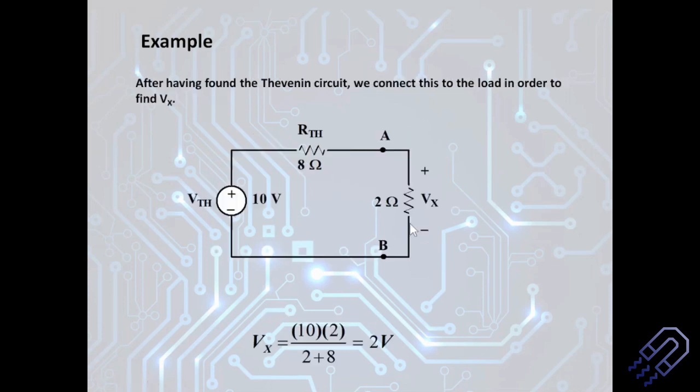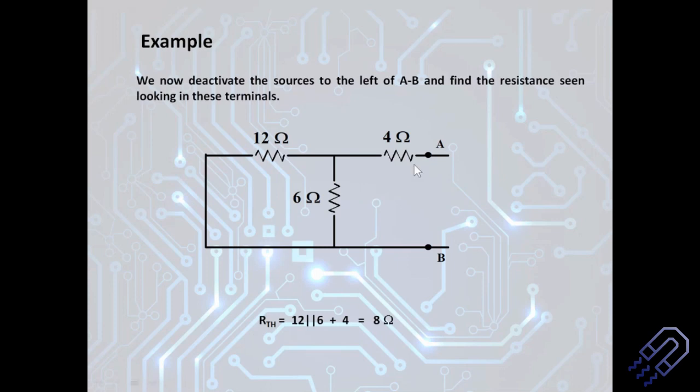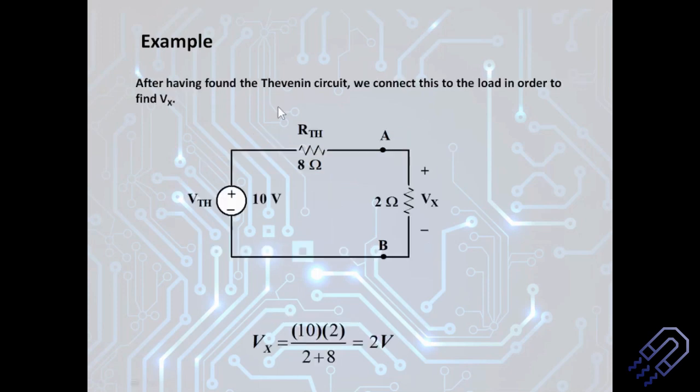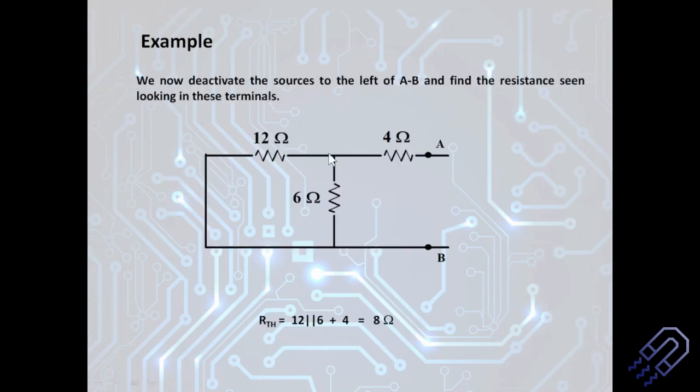So there is one resistance 4 ohm, okay. And then this is connected to a set of two different resistances. So what we have to do is we have to see that this 4 ohm is actually having no current division, but at this particular point, which is basically called the principal node, if you remember, the principal node where more than two components meet. So there are 4 ohm, 12 ohm and 6 ohm, all three of them meet at this particular point. So this is a principal node, okay. This is a simple node. This other end is basically a simple node because here you have got one end of 12 ohm and one end of 6 ohm. So this is a simple node, but this is a principal node.